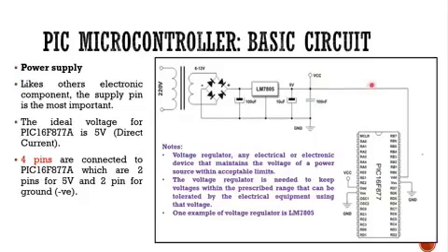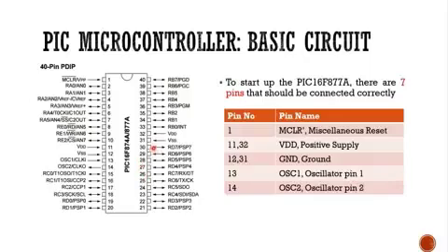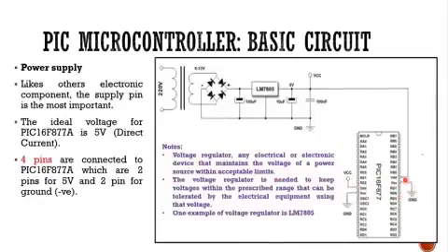So you can see here how you connect it. For VDD, pins 32 and 33, 10 and 11, these also need to be 5 volt, and then ground.